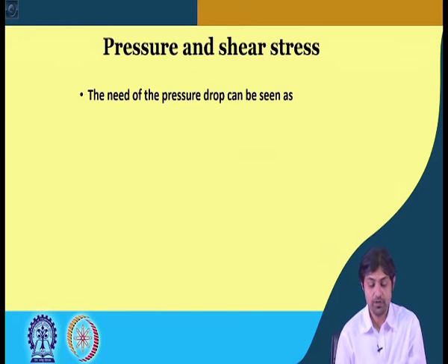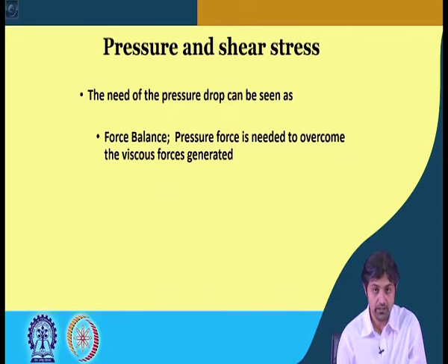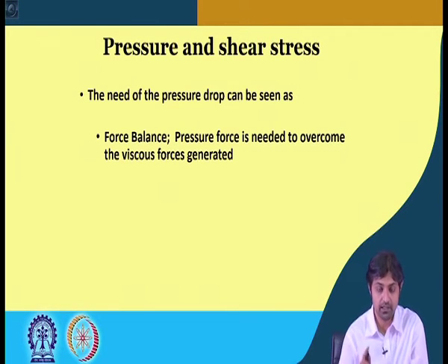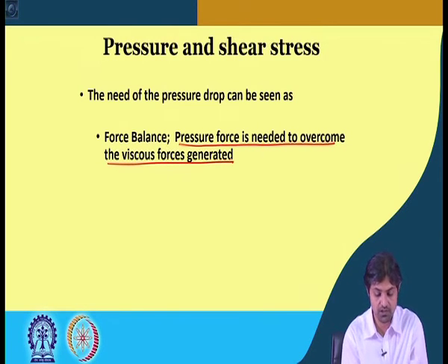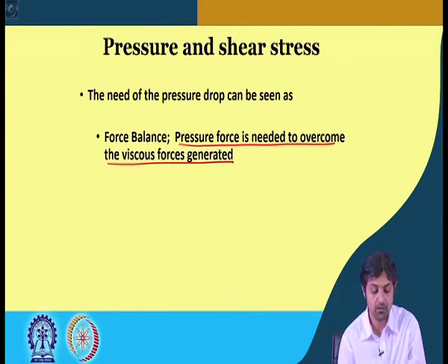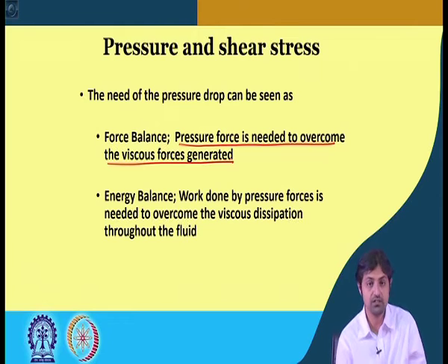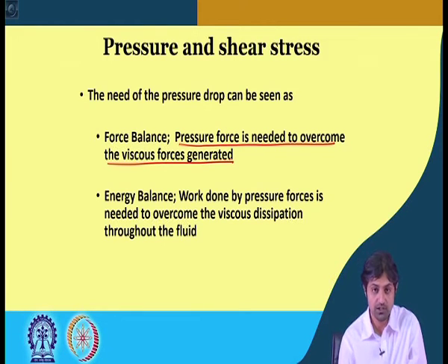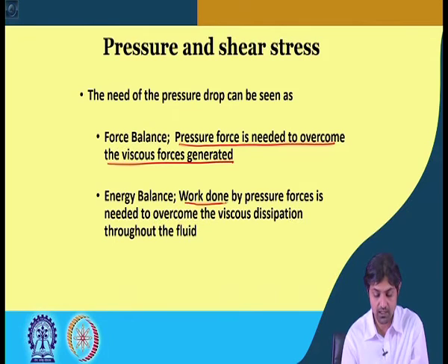Now, the need of this pressure drop can be seen in terms of force balance: the pressure force is needed to overcome the viscous forces generated. In terms of energy balance, we can say that the work done by the pressure forces is needed to overcome the viscous dissipation throughout the fluid.